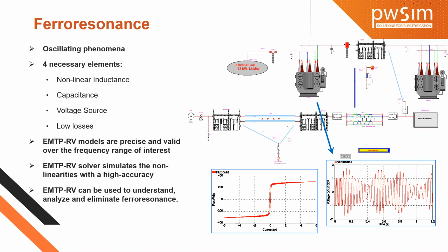Because of the ferroresonance, the voltage or currents suddenly rise to some other steady state from the normal steady state. So from one steady state it will reach another steady state. It will take more than 400 to 500 milliseconds and it will continue. After that it is reduced again. So it is very important to study ferroresonance applications. In EMTP, we can find the different types of ferroresonance, like chaotic ferroresonance and achaotic mode. All these things we can perform.